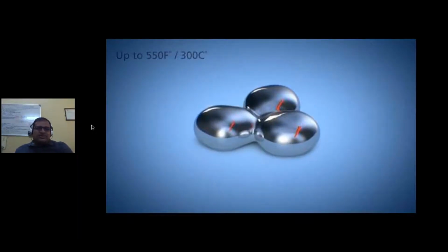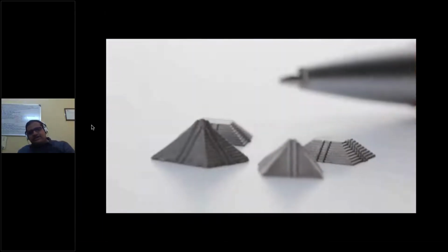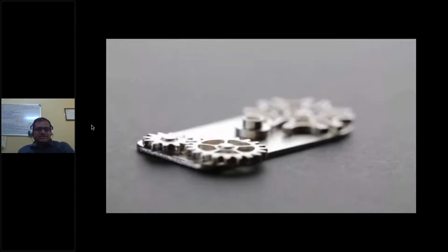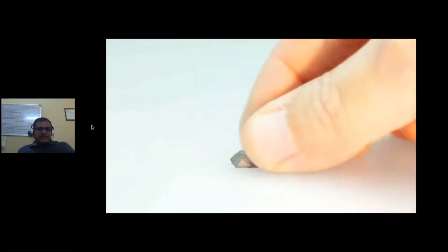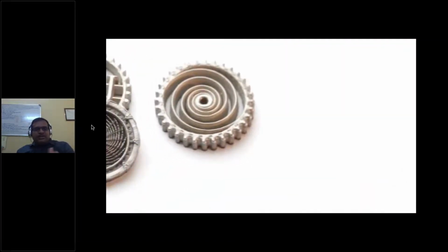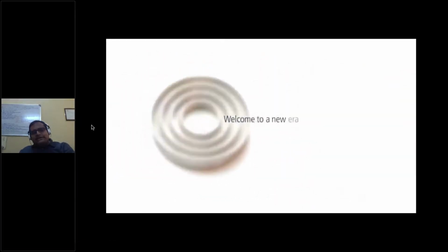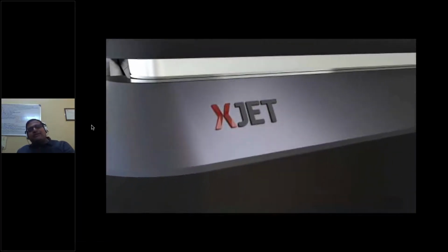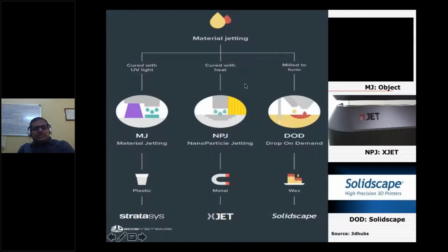And then this is what you are going to get, droplets of metal, and it will be with the liquid. And here the biggest advantage is that you are able to reduce your layer thickness further. So 250 in FDM, 25 in SLA. Now it is 2 to 5 microns I'm talking about. That is the layer thickness which you are going to use here. So that's about metal 3D printing under the heading of material jetting, right? That is the development happening nowadays.